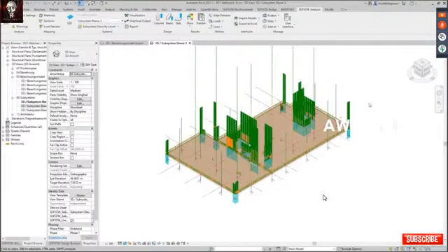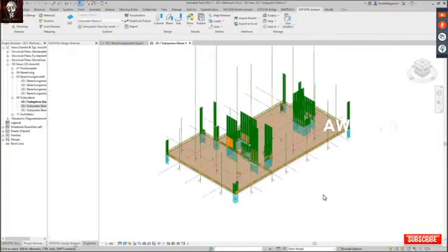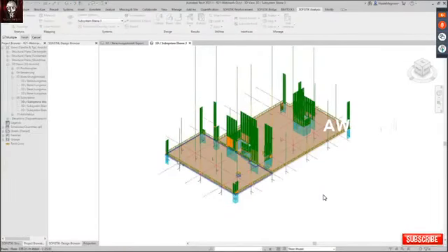So I already took care of the load of the finite element analysis, and now I would like to go to the design. For this, I will make sure the design browser of SOFiSTiK is activated. This is this side panel here, which was for me behind the properties. I will start the slab design command and select the slab element which I want to design.